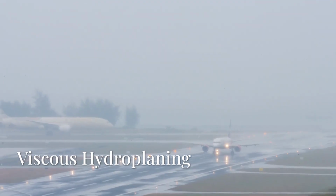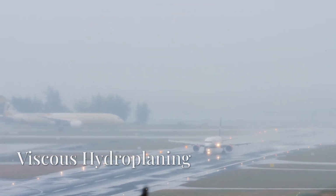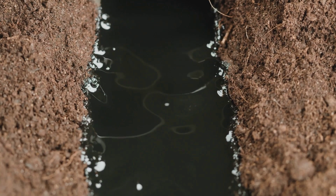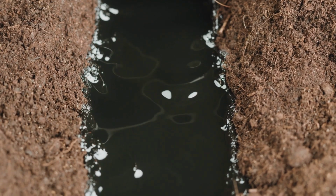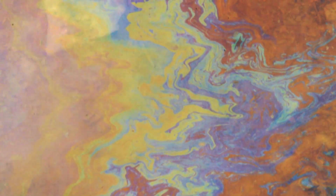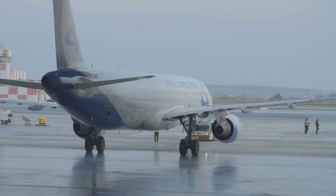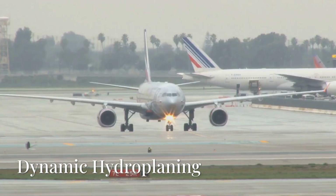Let's explain the different types of hydroplaning a pilot might encounter. First is viscous hydroplaning. This happens when water on the runway is mixed with things like oil, which reduces the surface tension. That makes it much more likely for hydroplaning to occur, even if you're moving at lower speeds or the water isn't all that deep.